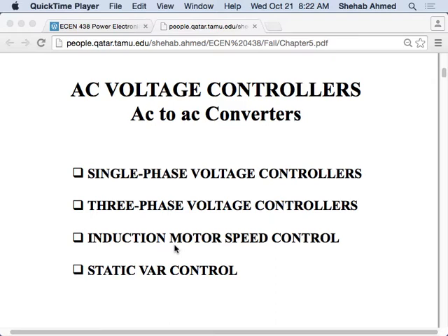We said that if the transformer has this time-varying MMF, then it will develop the back EMF voltage across its winding, which will limit the current that's coming in, right? If you take a voltage source and apply it across a piece of wire, what's going to happen? You will have a huge amount of current. It's a short circuit, basically.